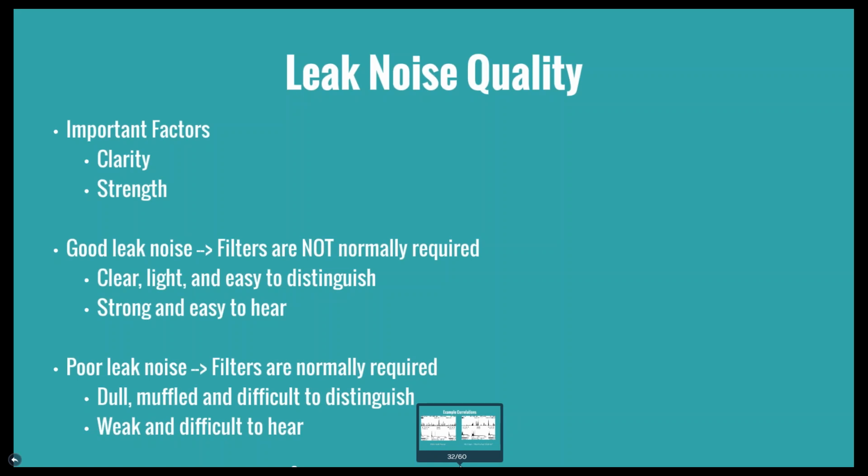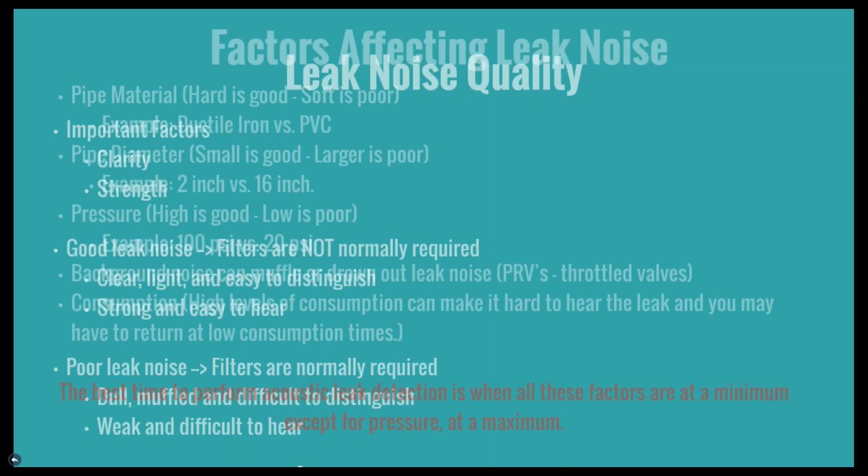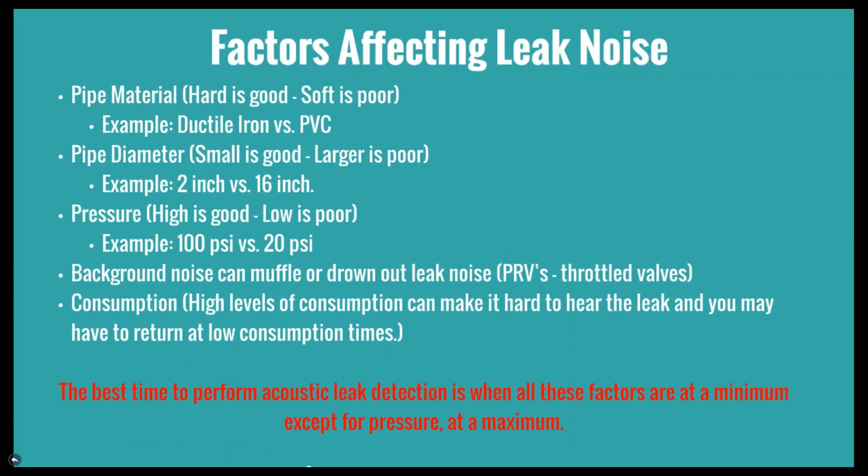So, some good leak noise where filters are not normally required. They're clear, and we'll show this in some slides coming up here, just what the peaks look like when you're getting a good leak noise. And again, the more you utilize your equipment and/or your contractor that's doing this, the more experience they have, the better they understand what good noises look like and what poor leak noises look like according to your frequency curves that come up.